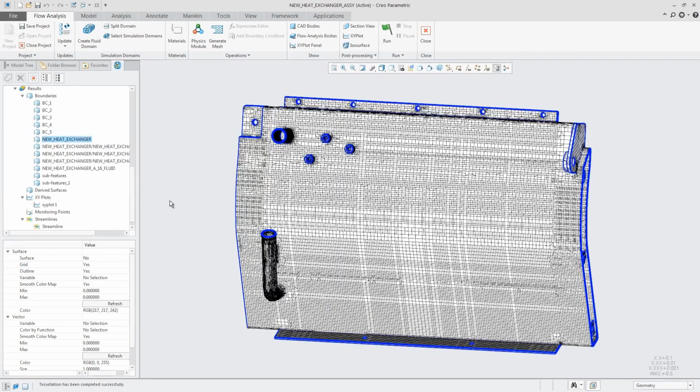And looking at the mesh here, you can see that in some of the flatter areas where there's a little bit less complexity, what the mesh has done is spread out that element size and made it a bit bigger because it's easier, less complexity. And in any of the areas where there's a little bit more curvature, a little bit more complexity involved, it's gone through and made each of those individual elements a bit smaller. So again, that's an area that you can have some manual control over, but in 99% of use cases, it's really going to be able to do that automatically for us.